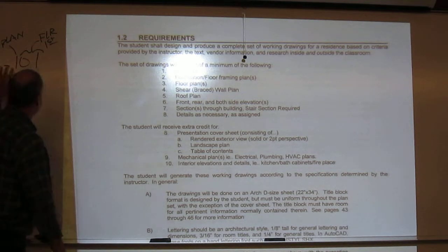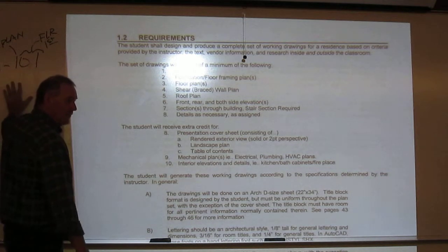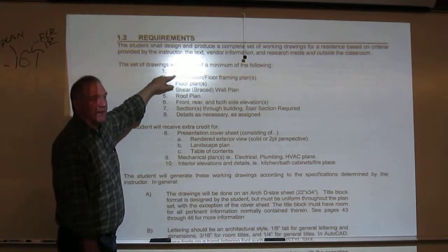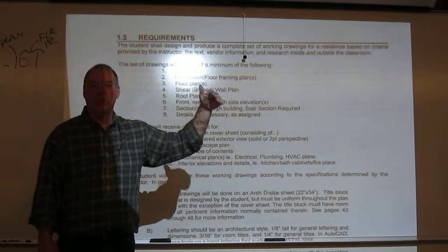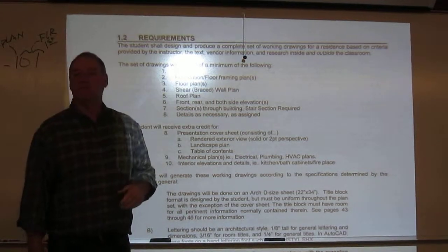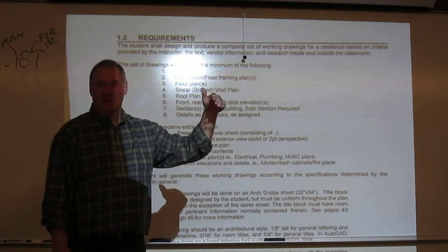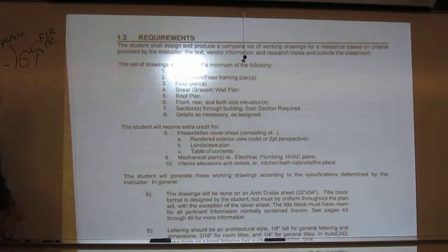Like if I'm doing that interior wall section, or interior bearing section detail like I drew up here, it would make sense to put it with the foundation plan. So hence it might be labeled detail 1, sheet 2, if it's my first detail. The stair would then be 2, and maybe I put it with the second floor floor plan. Now, that's kind of the order of it.